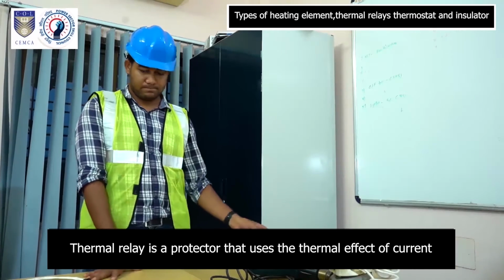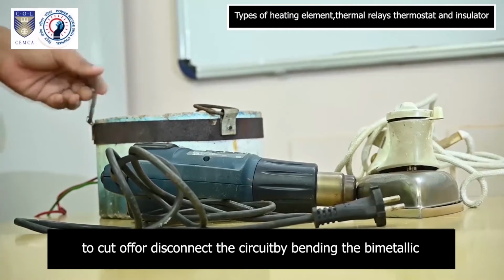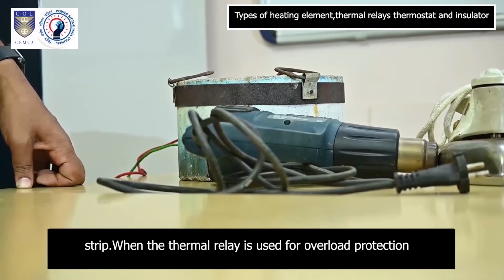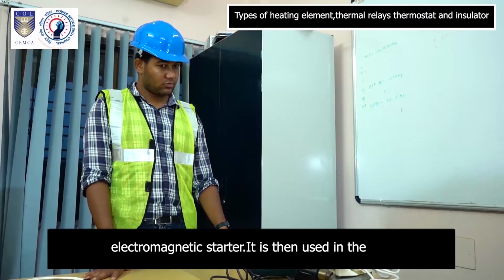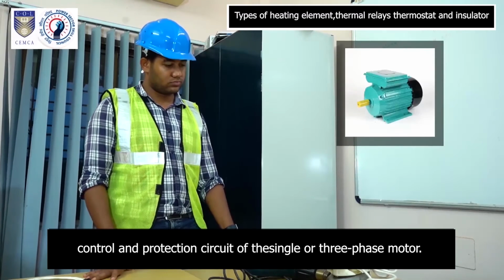Thermal relay is a protector that uses the thermal effect of current to cut off or disconnect the circuit by bending the bimetallic strip. When the thermal relay is used for overload protection in the motor, it often works with an AC contactor to form an electromagnetic starter. It is then used in the control and protection circuit of the single or three-phase motor.